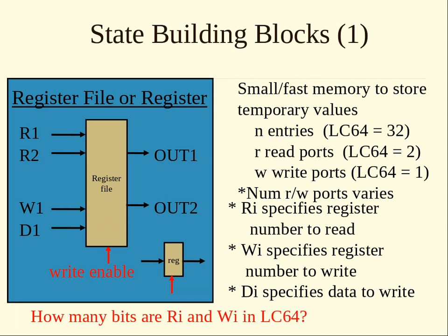All right, your register file, which is going to be a little more complicated, keeps track of all your registers. Now, in a 64-bit machine, how wide is one register? Take a guess. 64. Nice. All right, 64 bits wide. How many flip-flops is that? 64. I'm not trying to be tricky. Okay, so a single register is 64 flip-flops. That's it. That's how it is. A 32-bit machine register would be 32 flip-flops. But we're doing 64, so you have 64 flip-flops.